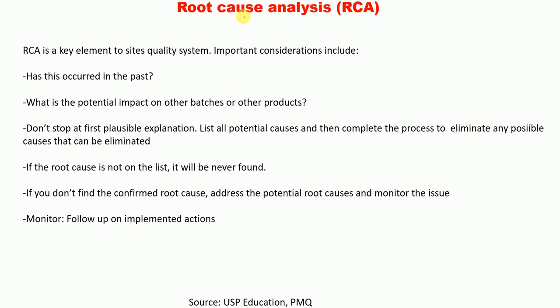The next topic that I'm going to discuss here is root cause analysis, a very important topic. What is root cause analysis, or RCA? Root cause analysis is a key element of the site's quality system. When we're doing root cause analysis, we have to pay attention to whether this issue has occurred in the past, and what the potential impact is on other batches or other products.